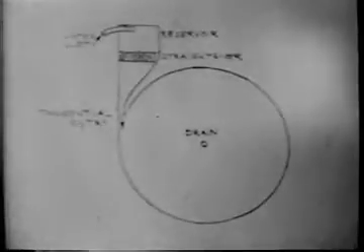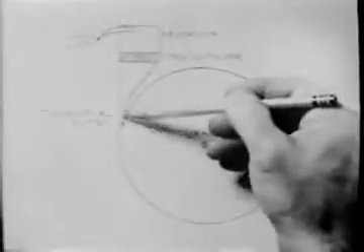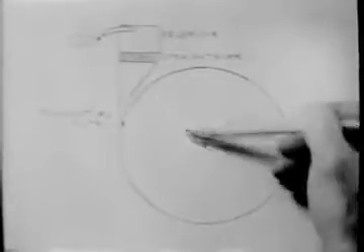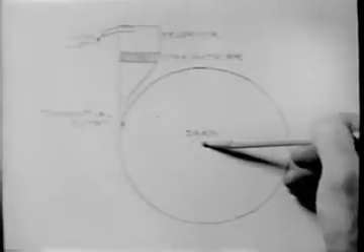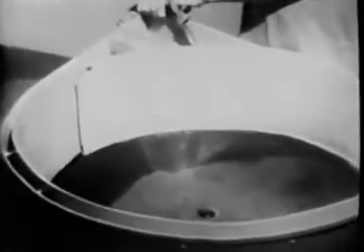This is the plan view of a spiral vortex tank. Water passes from the reservoir through a flow straightener and into the tank through a tangential entry. It spirals round and round in a very tight vortex and finally leaves vertically through a drain in the center. What will the vorticity meter do? It doesn't rotate. It moves in pure translation, like the needle in a compass box mounted at the rim of a rotating turntable.